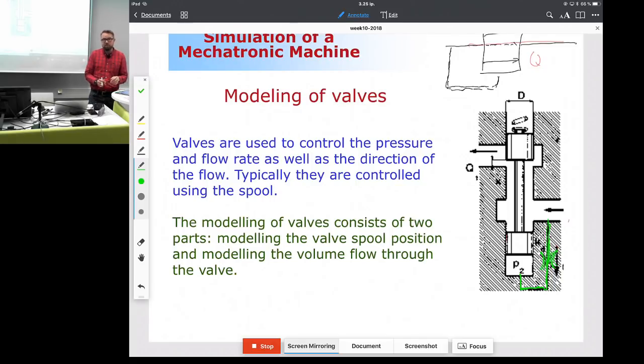Well, of course, a hammer is one that we can use to break the component to pieces and then finally measure it. Or a saw, flywheel and other stuff, we can break it. But we have to break it in order to get these parameters. We don't necessarily need to do that because the properties of this valve are actually measured already. And this information is provided in the manufacturer's catalog. So we can simply go in the manufacturer's catalog and take a look how it is. And that gives us an indirect way to measure these parameters. That's exactly what we're going to do.